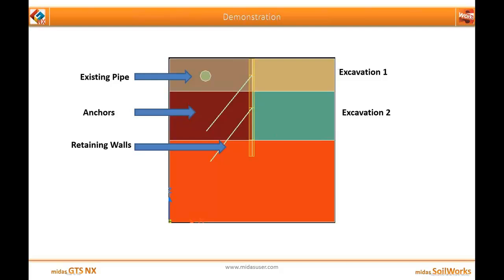So now I'll move on to the demonstration part. In the demonstration part today I'll be taking a 2D modeling of a simple excavation in which I'm going to do two excavation sequences, excavation 1 and excavation 2. The shoring system which I'm considering consists of a retaining wall with anchors. I'd also be showing you, if you want to pre-stress your anchor, how one could do that. And I have an existing pipe. So I would be initializing my stress condition considering the pipe, and I will see the effect with and without consideration of this pipe for my initial stress initialization. So I will just open Soilworks for you.